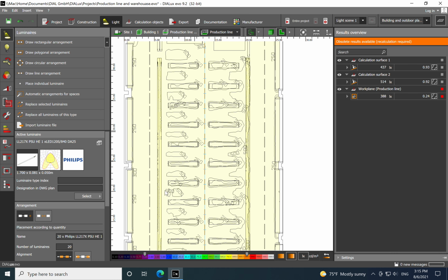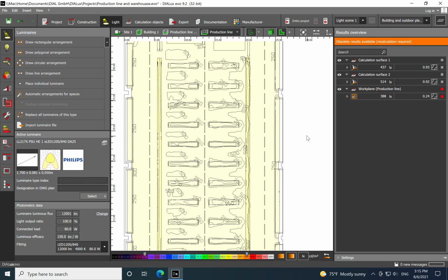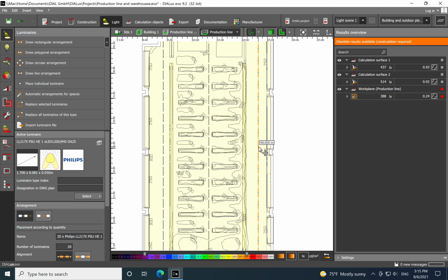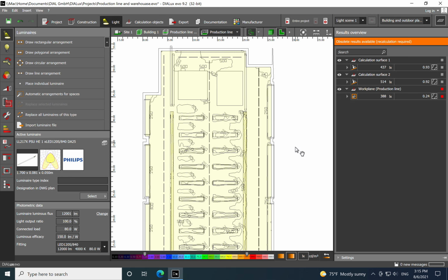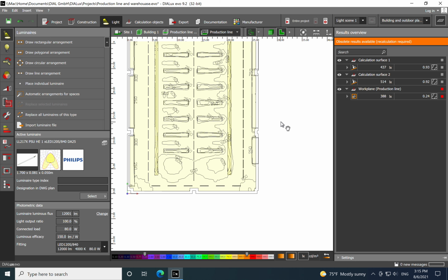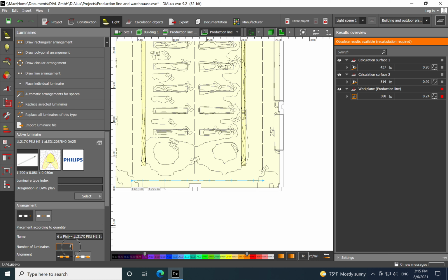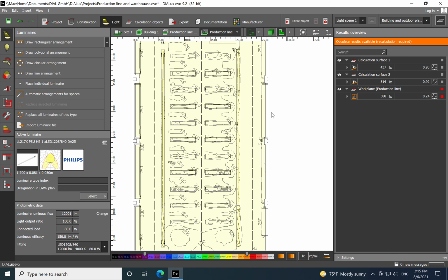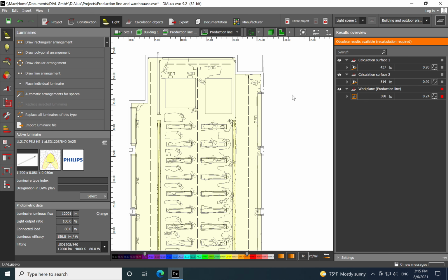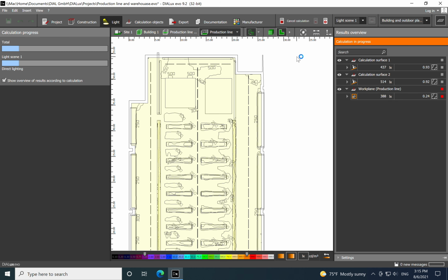And again, also on this side, so we place 25, 24, also in the middle, and also on the side we will go with the same amount of luminaires. Just double check that we have the right numbers, and maybe here, because I see a corner, we should place, let's say, 8 luminaires, just to help us have better uniformity on the corners. Upper part looks okay, and then we just run once again the lighting simulation, and let's see the result.